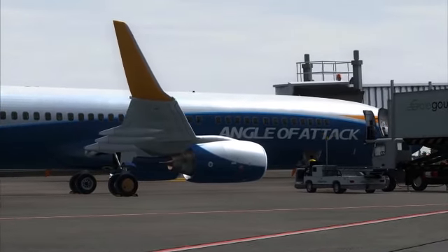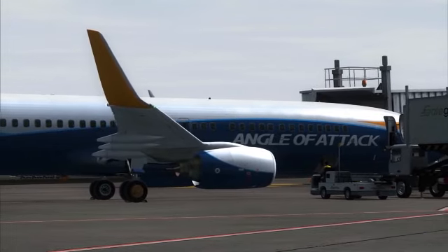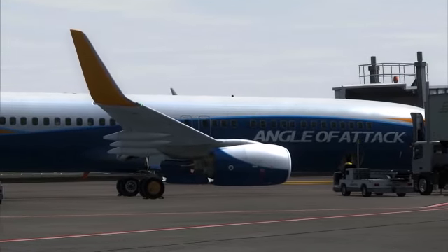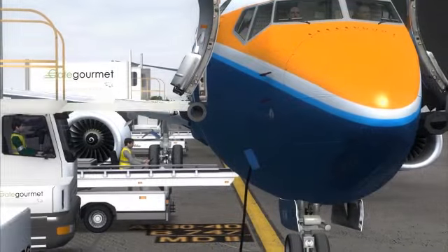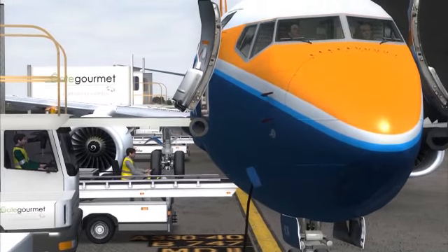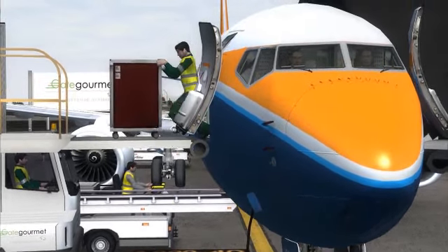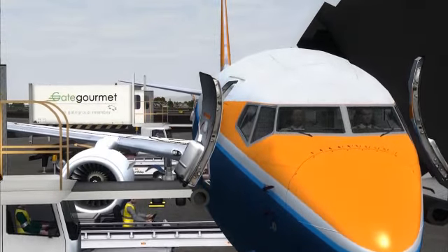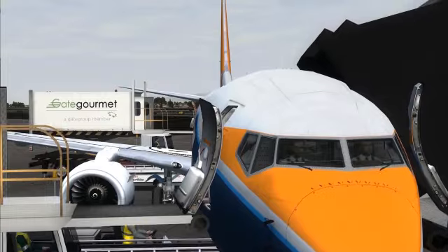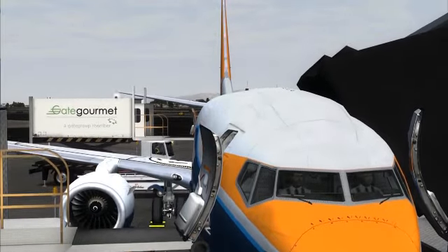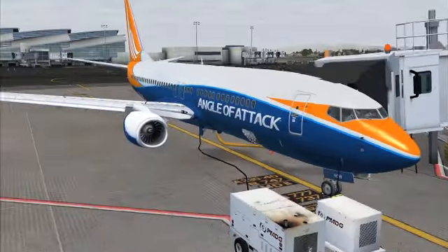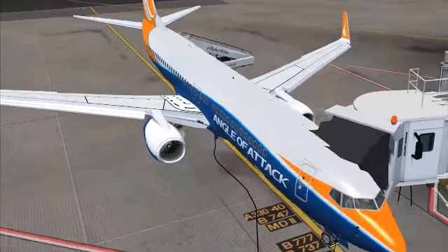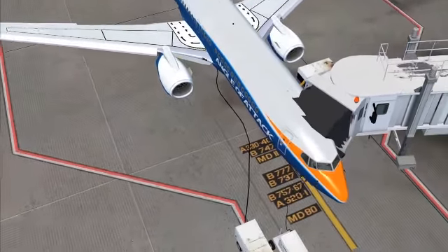It's fundamental to know that for an airline to start a scheduled service to a specific airport and runway, the aircraft must be able to demonstrate that it will be able to brake satisfactorily without the use of the reverse thrust system, as this is only an extra aid that's available to reduce the landing distance roll and tire wear and tear. We also discussed some of the cockpit indications associated to the engine system.